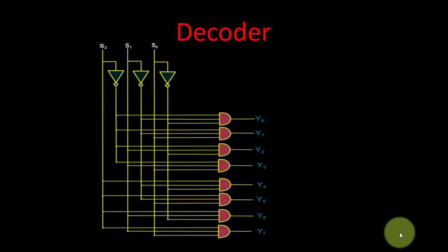Now what this decoder will do is, we give the particular code to the decoder, and it will tell which number the code belongs to. So it works opposite to the encoder. In the previous case, when we gave input as 7, we got the code as 1 1 1. Here it will be opposite. If we give the code, it will give the number. Now let us start with 1 1 1.